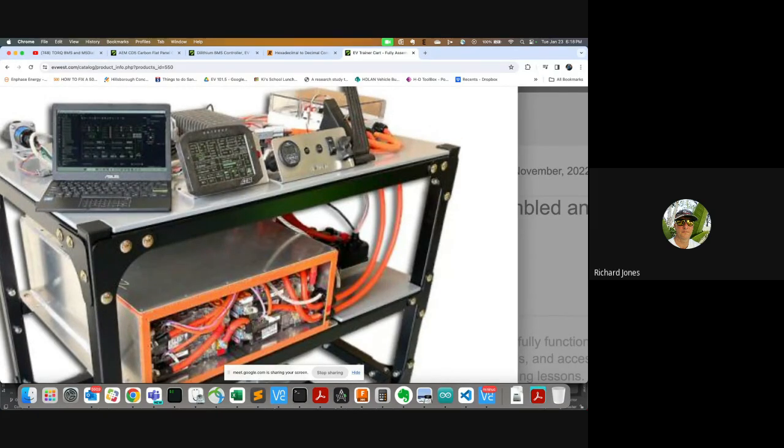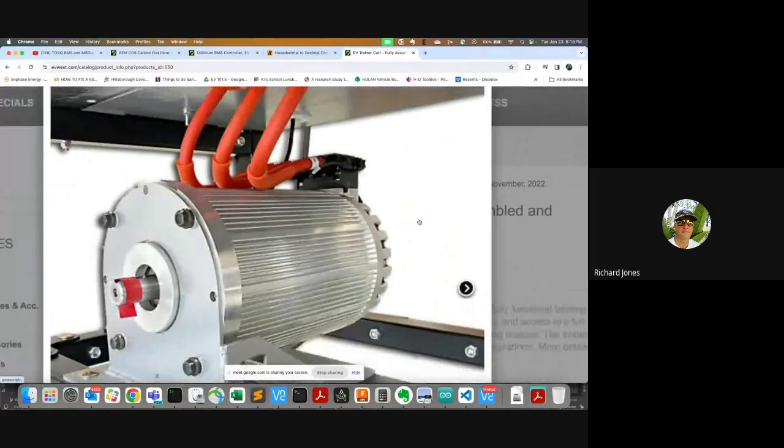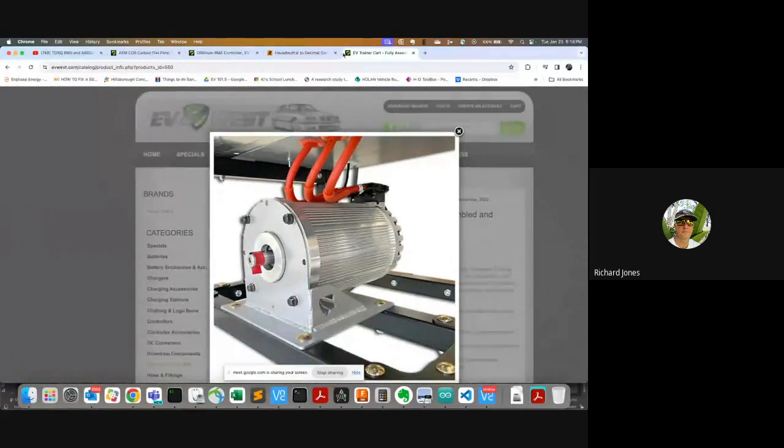But when you're teaching, it is good to know how to troubleshoot when the CAN bus isn't working, right? Or parts of your BMS aren't working. If the CAN bus is working, but you have a cell temperature sensor that's not correct, the troubleshooting techniques are good to do. Nice.